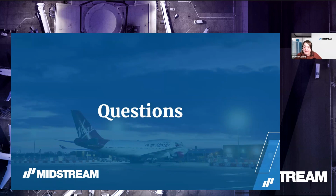So first up, our first question: can you mix different color temperatures on an apron, and is it visible to the eye? Natasha, do you want to answer that one, please? Yeah, I can take that one. We've been asked this a few times, and the simple answer really is that it's not good practice to mix color temperatures, purely because it is visible to the eye. If you're mixing 4,000 Kelvin and 5,000 Kelvin, there will be a visible difference, with the 4,000 Kelvin being a warmer light and the 5,000 Kelvin being the more blue light. So we typically say that in one apron area, it's got to be the same color temperature.